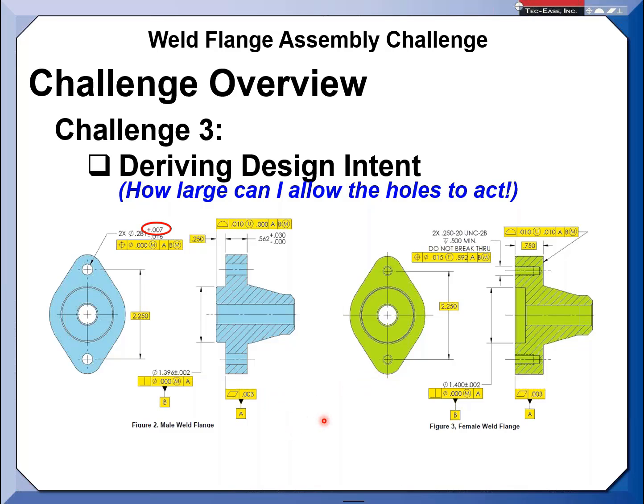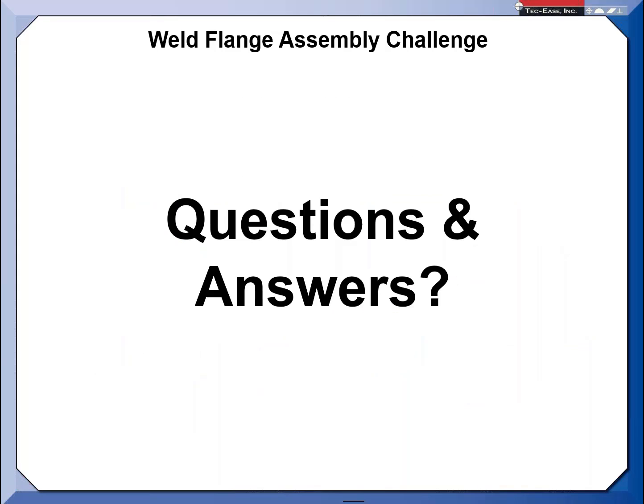I have gotten a lot of responses about producibility and all that. There's much more you can get involved in, dealing with producibility, statistical probabilities and things like that. But really, it's just pretty simple. How small can the hole be? How big can it be? And can you prove out mathematically that if the parts are compliant, it will go together? And that's pretty much it.